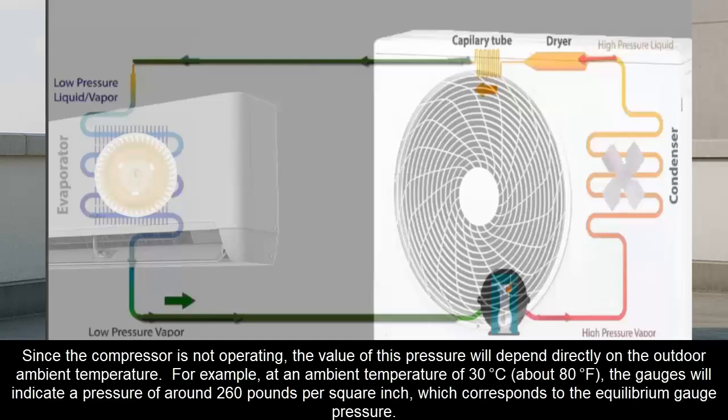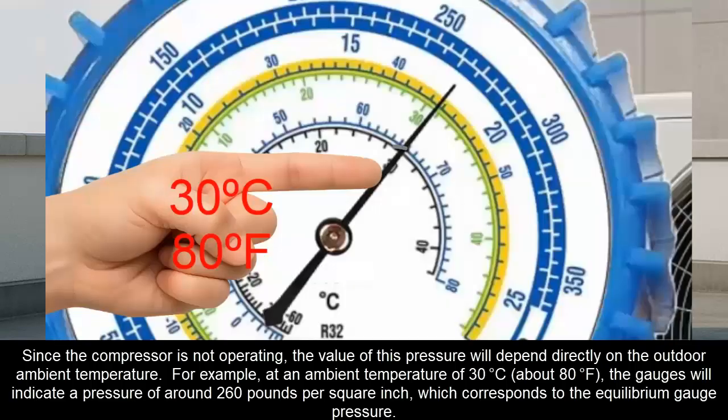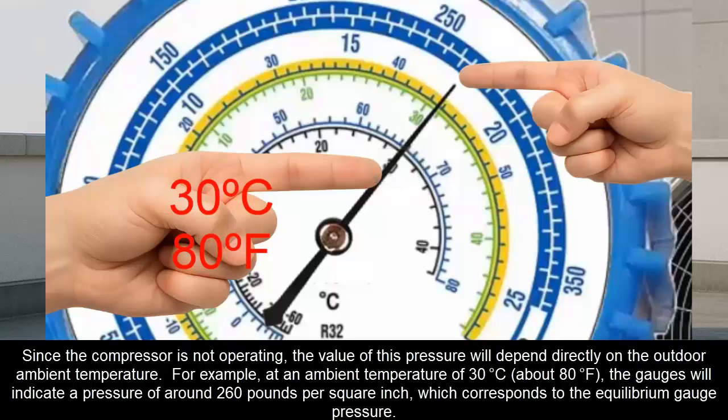For example, at an ambient temperature of 30 degrees Celsius, about 80 degrees Fahrenheit, the gauges will indicate a pressure of around 260 pounds per square inch, which corresponds to the equilibrium gauge pressure.